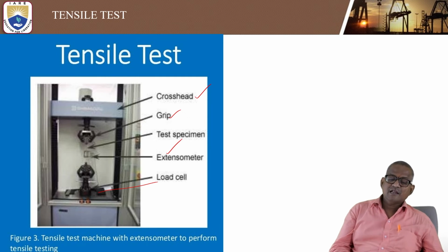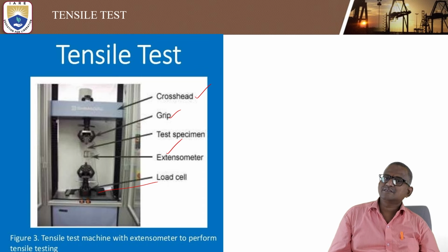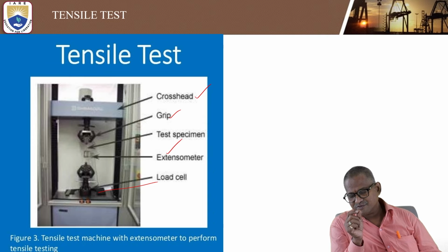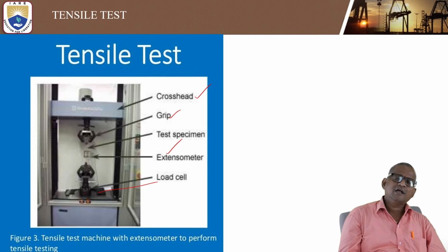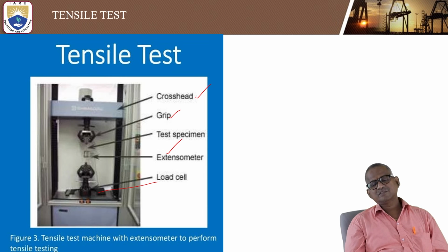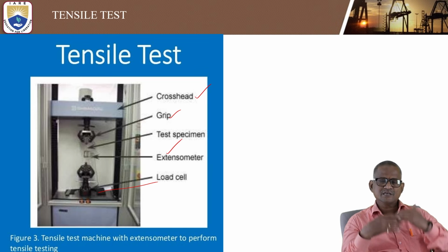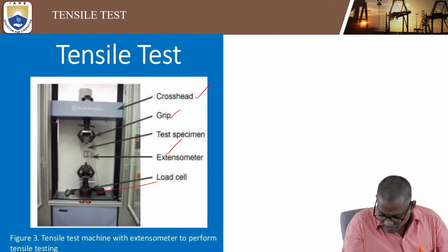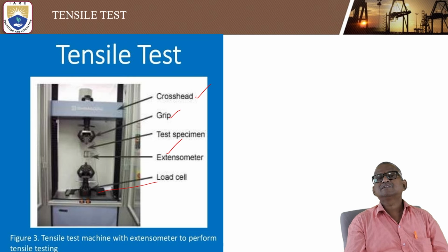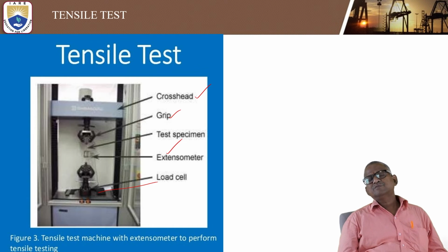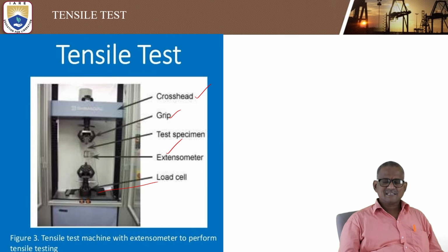Similarly, with the extensometer or micrometer, the resolution is about 10-15 microns, and based on that you start. Nowadays colleges write proposals through AICTE and similar schemes, and the operators can explain how to perform the tensile strength test. This comes under the destructive test.